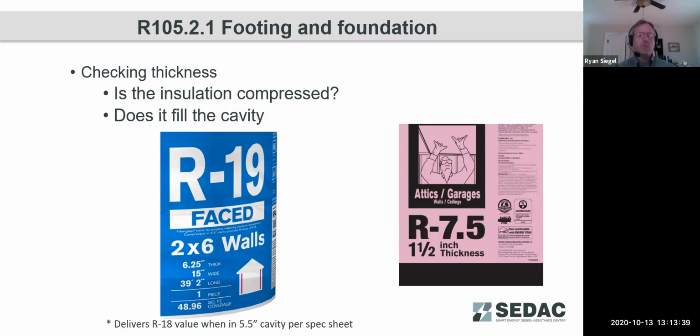So once we've identified and figured our R value, next is checking for the thickness. And as I noted earlier, if you compress insulation, the R value will change, and the total R value will decrease as the insulation is compressed.